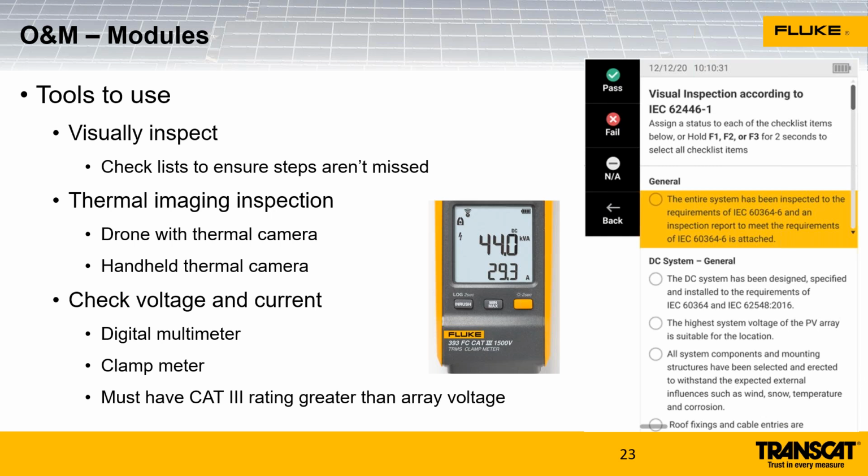So if you try measuring current with the probes of your multimeter or even with a clamp meter, using those probes is essentially short circuiting that PV string, and most meters are not rated for that current level. At most they're rated for 10 amps. So at least you're going to blow the fuse of the meter in many cases, and at worst you're going to cause damage to the meter, which could be a pretty severe safety hazard to the person holding the meter.